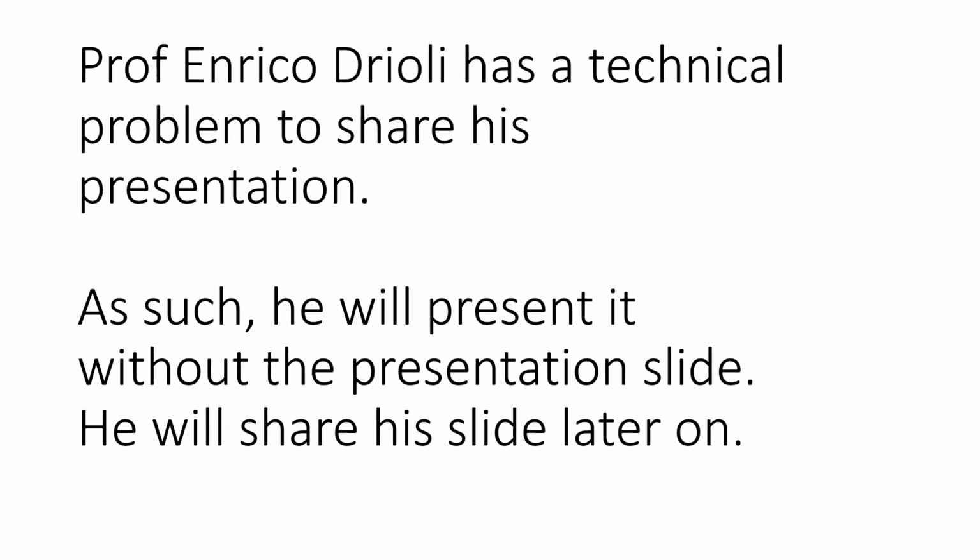However, if you look at what is happening in research, you will see that the situation is changing. There is a new methodology, new technology appearing, trying to overcome the limits of reverse osmosis, of the osmotic phenomena. These new technologies are based on membranes very different from the traditional ones we are using in RO. They are no more hydrophilic membranes. They are no more dense membranes. They are microporous hydrophobic membranes.